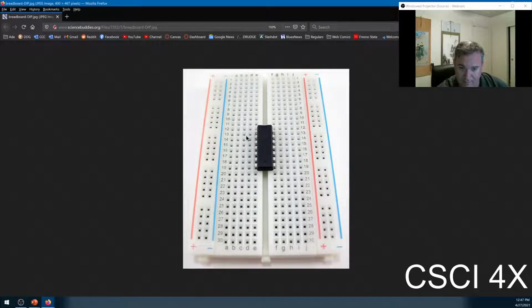And so you can supply inputs to, you would usually run, where is the thing here? Yeah, you see where the divot is right here. And so if that one is VCC, you would run 5 volts connecting this to here on any of the 13s, and then the chip would be supplied with power. And then you'd run ground from any of the ground pins into any of the ones on 19 here, and then it'd be supplied with ground.